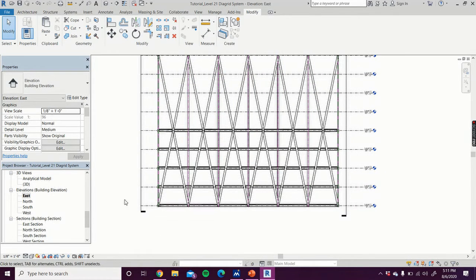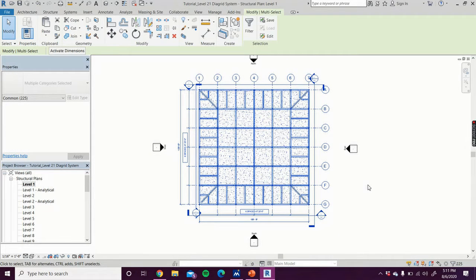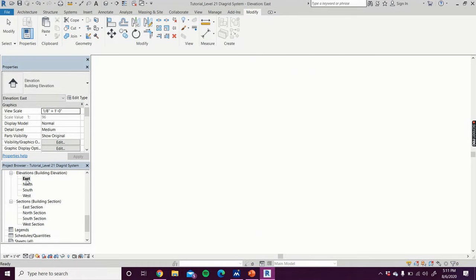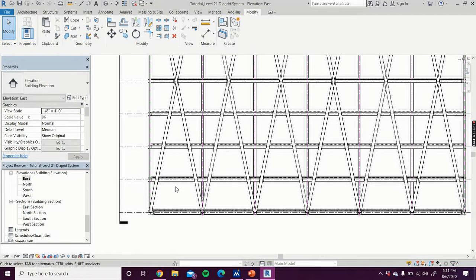And before you do, just make sure that all of your beams and floors are already ungrouped. So you're going to want to go through, check each floor, select everything, and make sure there's no dotted boxes around any of your beams, because in the next video we're going to be color coding, and you can't have any of these array boxes around them. And just make sure that you already have your floors and beams and that they're all in the right places. You want to make sure you have all of your dimensions correct before you copy and paste these. If there is a mistake, you can always change it later, but it's just easier to do it now and make sure everything's right, then copy and paste at the very end once you're all done.